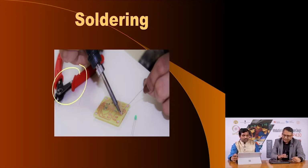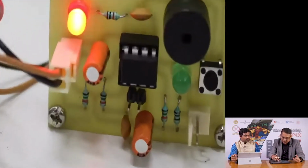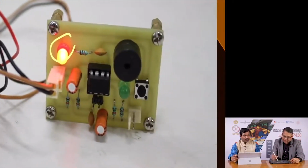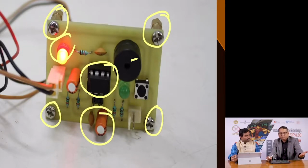Once you do that, you are left with a beautiful PCB where all the components have been inserted rightly. As you see here, the resistors have been nicely bent at 90 degrees, so that they are easily inserted in the given holes. Here is an LED, it is powered with a battery. Here is a buzzer, this is the 555 IC. Here are two capacitors, one of them is an electrolytic capacitor, the other is a ceramic capacitor, and these 4 mounting holes with screws allow you to put it on any surface without a danger of making unwanted connections, because the surface might be conductive.